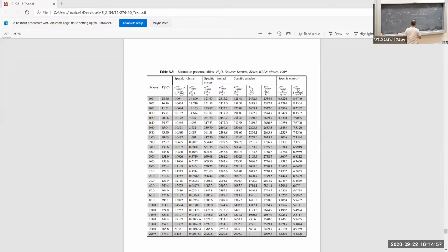I should have a negative sign there. Kinetic energy falls. I just realized that. I dropped the negative sign. Delta KE from 1 to 2 is negative because velocity going in is 80, velocity going out is 50 meters per second. So kinetic energy falls, so I get a negative 1.95 kilojoule per kilogram.